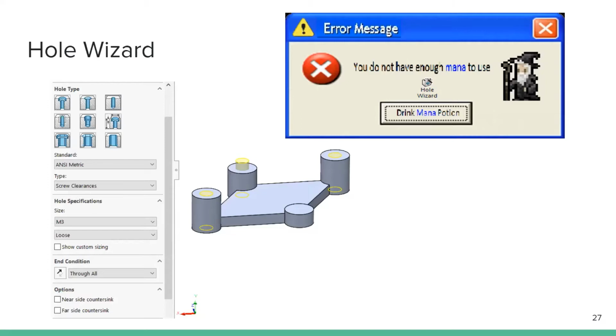So you can, in this example, tell it that you want a clearance hole around an M3 screw, and then it's going to know, because it already knows what dimension that should be, and it just makes it easier for you to not have to look things up all the time. So it took a little bit of getting used to for me personally, but very handy. Would recommend. I still mess it up. Takes like 5 minutes to get it all straight.